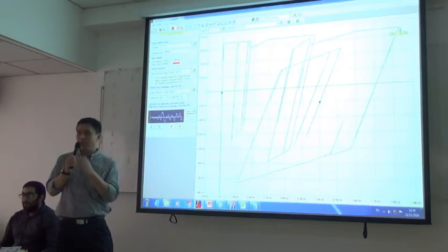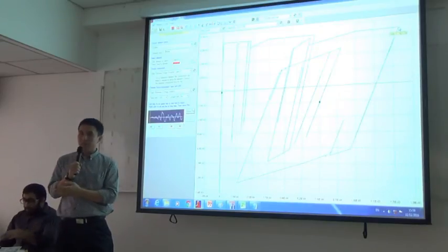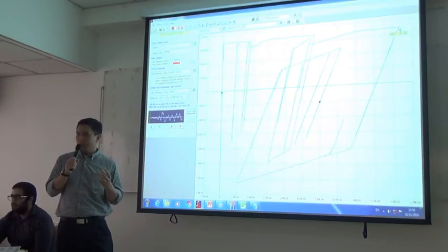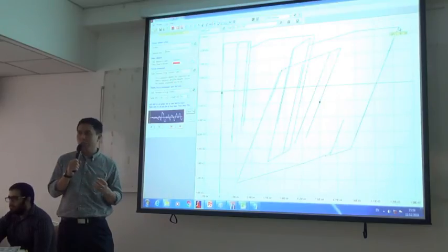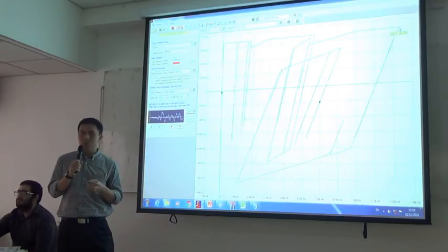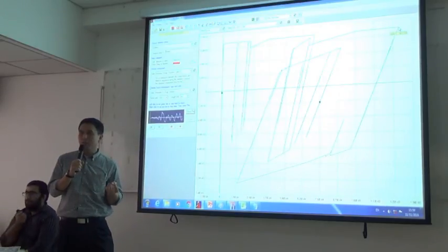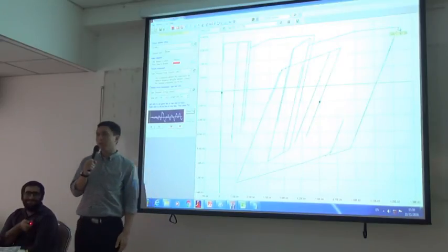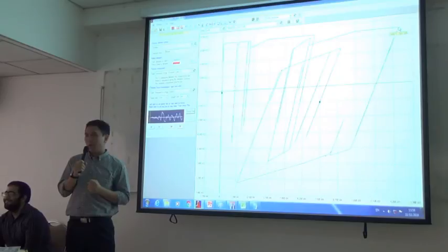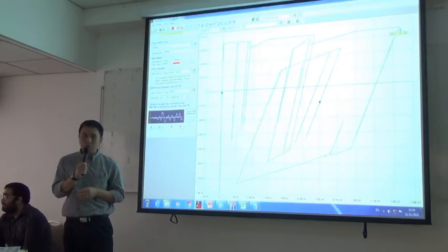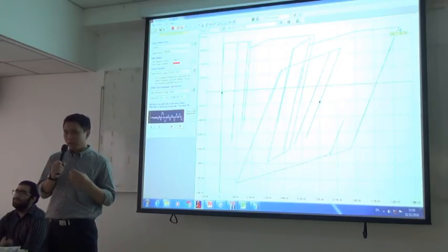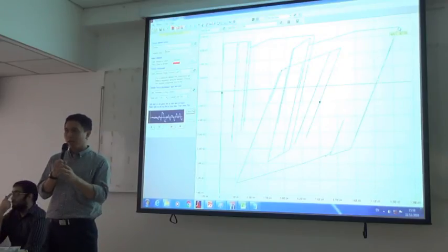So we have to extract the results in text files for each component that we would like to check. For the shear walls, we extract the section cut forces to check the shear wall shear, axial strain values to check the flexural response for concrete crushing strain, yielding strain, steel rebar strain, as well as the rotations of the coupling beams. And also we have to extract the axial force, shear force, and moment values for the columns in each group from the text file, and copy to the Excel file for the post-processing.